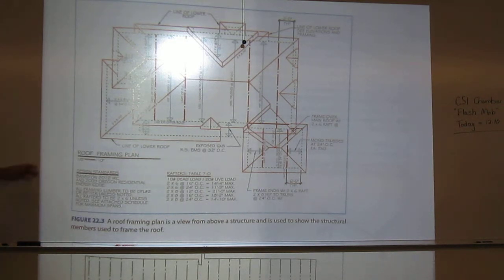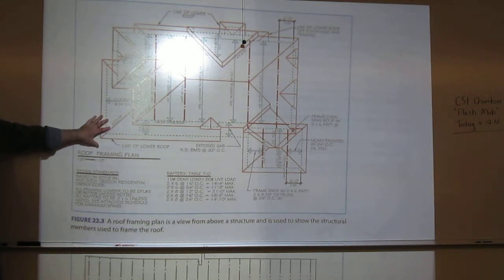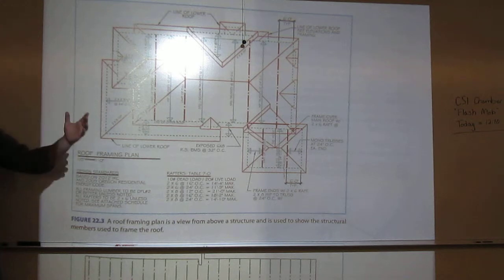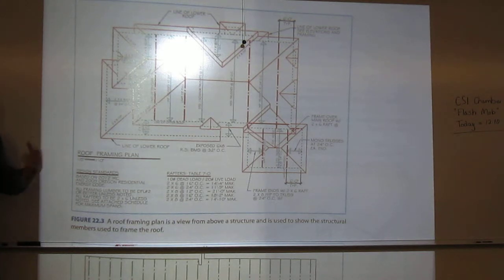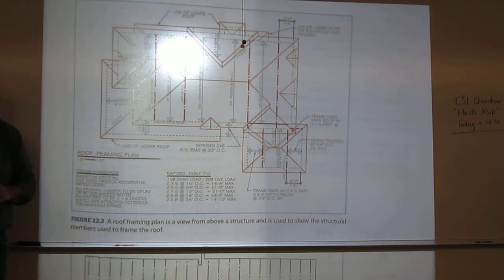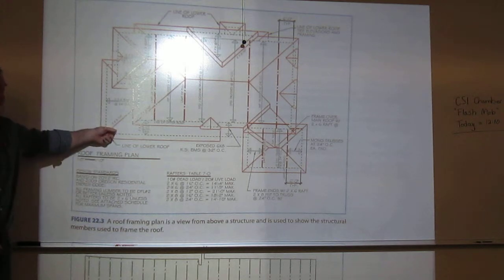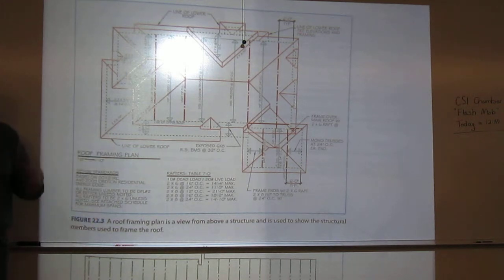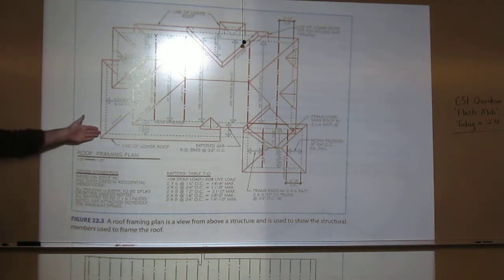Remember, when you do a roof plan, you can go 1/8. But like I mentioned during the class, it looks kind of weird. People can't make the jump, I've found. A lot of people struggle making the jump when they're looking at floor plans at a 1/4, and then they look at an 1/8 and it's half that scale. So many times I'll take a roof plan and do it at a 1/4 just to keep that continuity of my plan set going forward. So I would suggest that you take it at a 1/4.